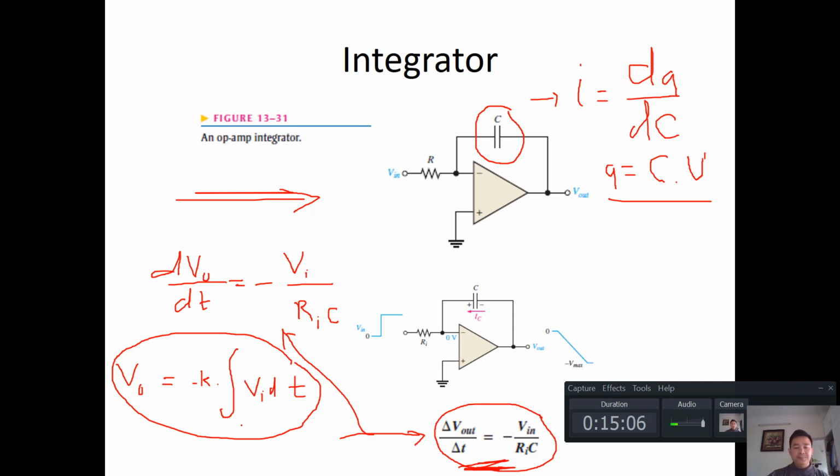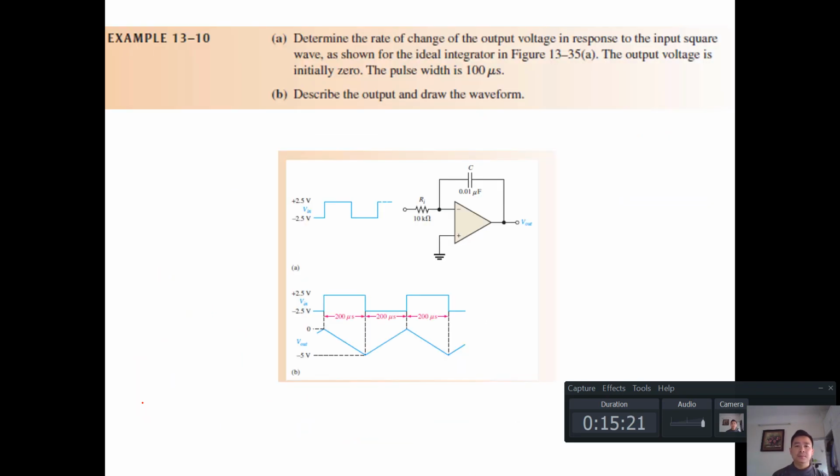You can see that if the input signal is V in, the output is a function of the integral of V in. This is one application of the integrator circuit. You can change a rectangular form to a triangular form of a signal.